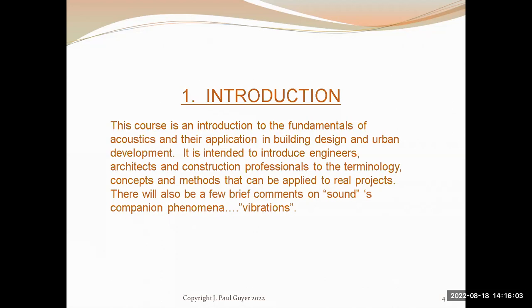A companion phenomenon to sound is vibrations. They both start in a source room with something vibrating. It might be a violin string. It might be a fan in a fan room spinning around and bouncing around and making noise. The distinction between sound and vibrations is that sound tends to be largely a through-the-air phenomenon, not exclusively, but largely, whereas vibrational energy is primarily transmitted through the structure of the building, the beams and the columns and the decks and so forth.